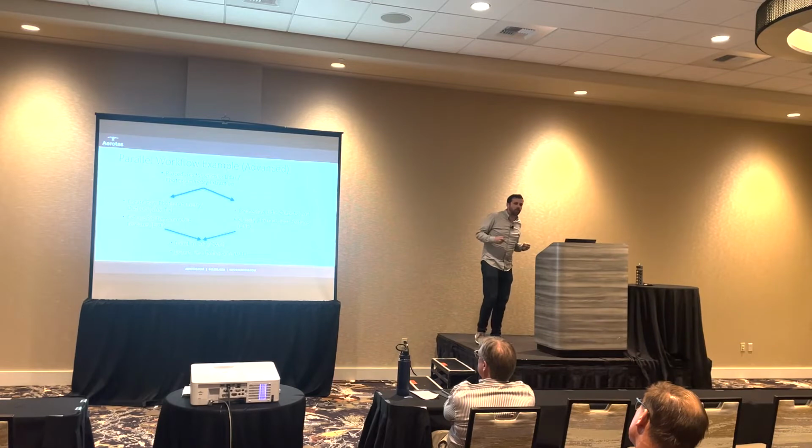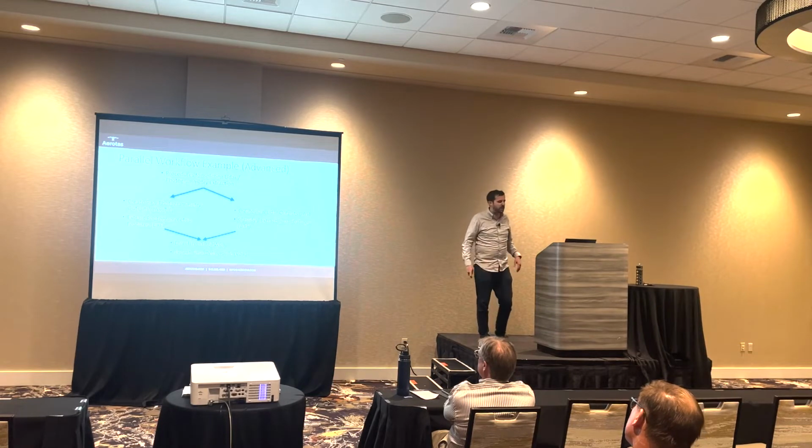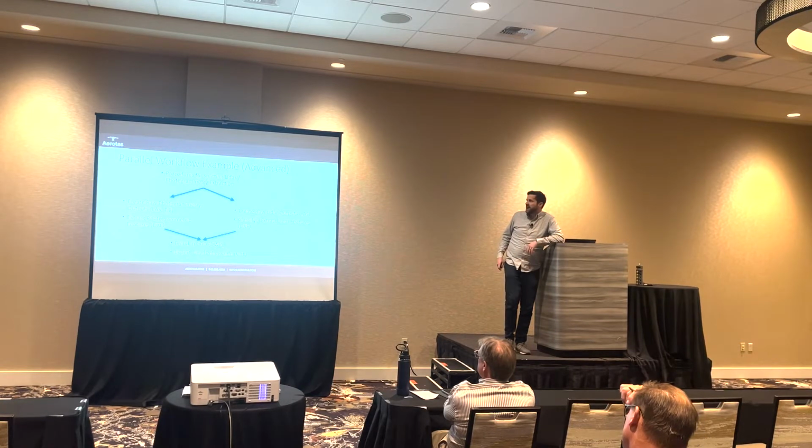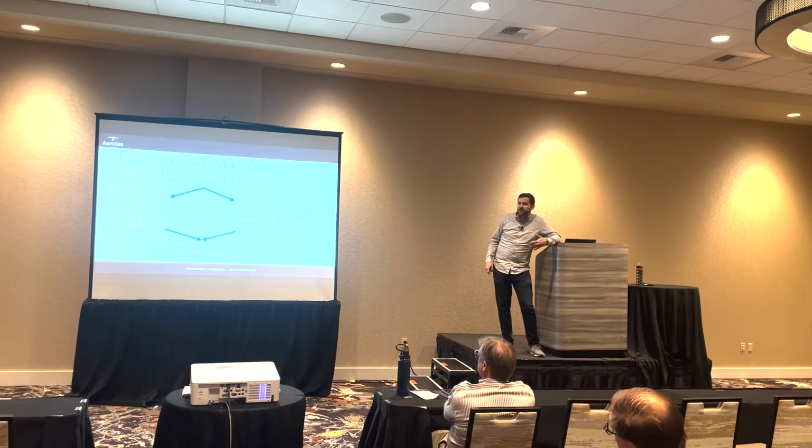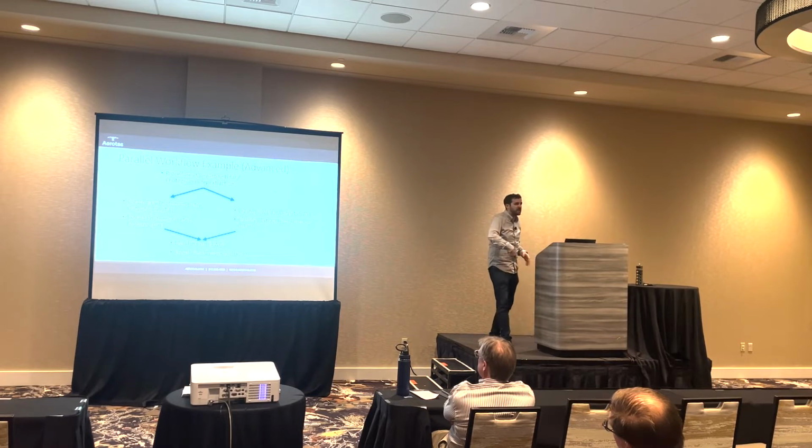So by the time you import it into AutoCAD, it just takes a little bit of QA/QC to make sure that everything lines up nicely. Also, if you follow a good enough workflow, make sure that everything is georeferenced as well, so that your photogrammetry data lines up perfectly with your LiDAR data, which should line up perfectly with all of your field data as well, your GPS or total station data.